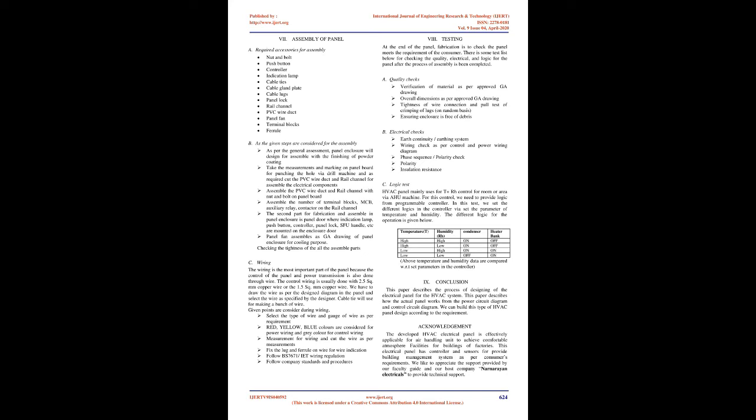As the start signal is released by the start button, the auxiliary relay will be energized and the NO contact of the relay will close, and the signal will be released to relay 2 of the VFD and its NO contact will close. As the NO contact of relay 2 closes, the supply will energize contactor K1 and the AHU fan motor will start at the nominal speed as programmed via the VFD.